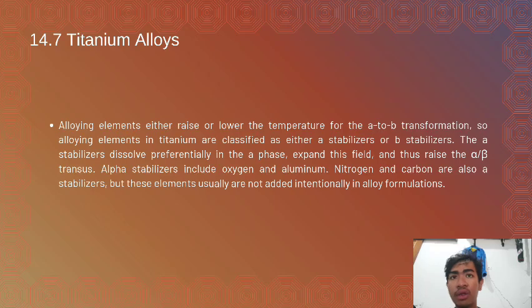Titanium and titanium alloys are heat treated in order to reduce residual stress developed during fabrication, produce an optimum combination of ductility, machinability, and dimensional and structural stability, increase strength, and optimize special properties such as fracture toughness, fatigue strength, and high temperature creep strength. The response of titanium and titanium alloys to heat treatment depends on the composition of the metal and the effect of alloying elements on the phase transformation of titanium.